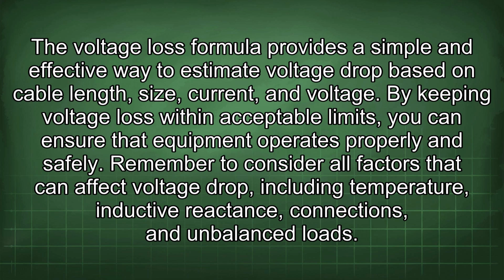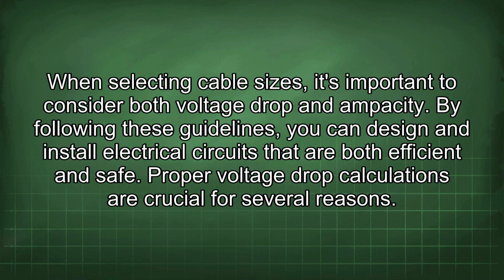Remember to consider all factors that can affect voltage drop, including temperature, inductive reactance, connections, and imbalanced loads. When selecting cable sizes, it's important to consider both voltage drop and ampacity. By following these guidelines, you can design and install electrical circuits that are both efficient and safe.